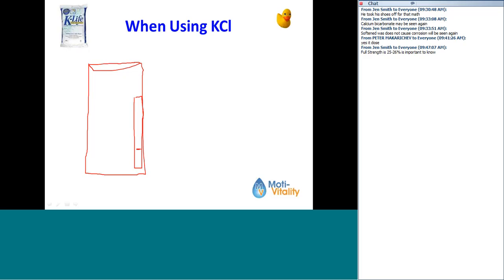So you put the salt in, and the salt's all down here, and here's the water level. Okay, so the salt level is filled to about here, but down below this water level is where the salt dissolves. And so basically when you go to pull the brine in, it sucks the brine up through the brine tube and into the softener, right? Because this is where it's all making brine.